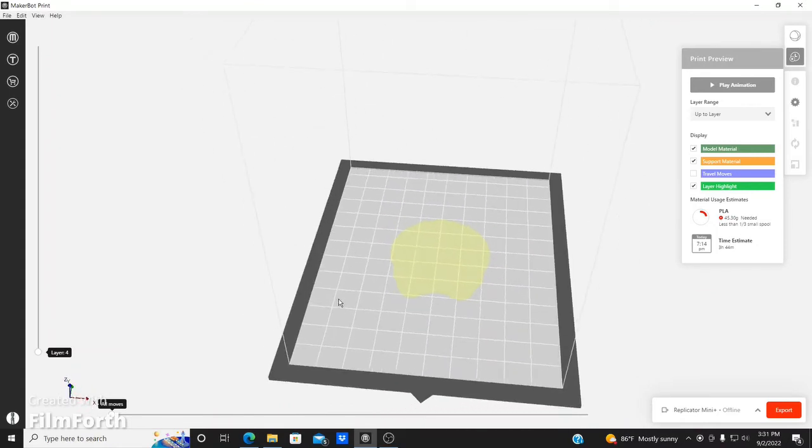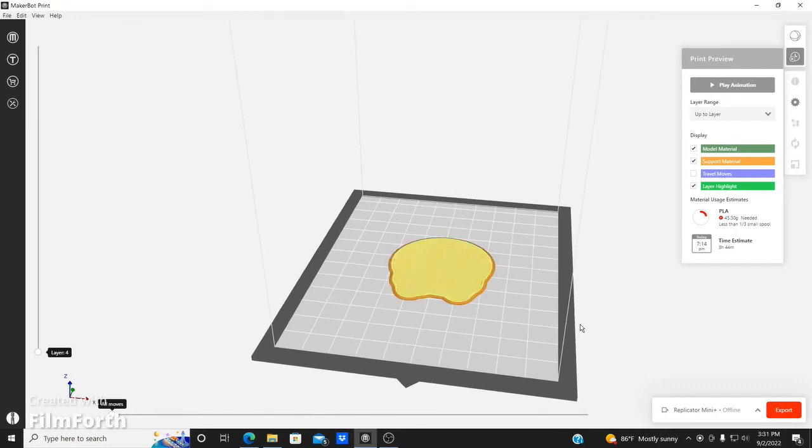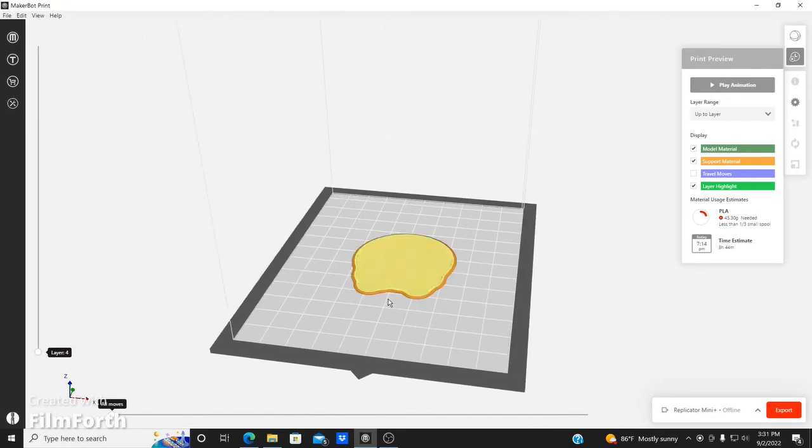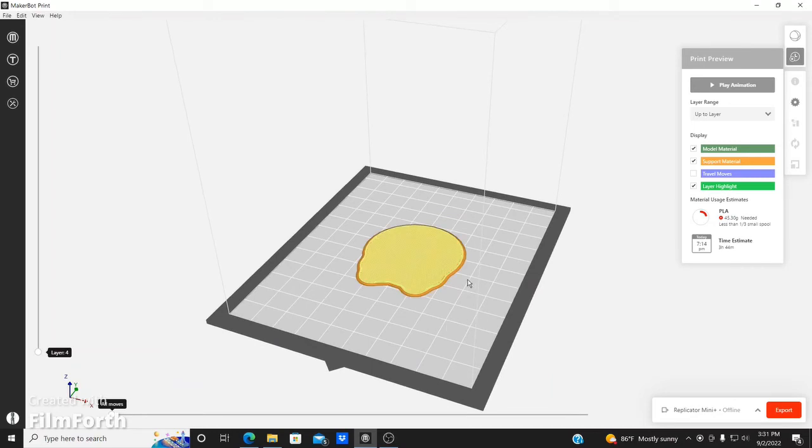There are 3D communities that play around with this, and they use different ways to resolve it. You can use hairspray, a glue stick, and masking tape, which is what you use for painting. You can use those 2-inch ones to cover up your build plates rather than those skinny strips. Most of the time, they will do a combination of all of it. For example, if I have a build plate, they'll put masking tape, then add either hairspray or stick glue, so that it'll stick much better. So it'll prevent that failure along the way.